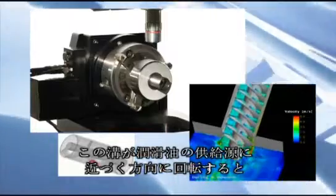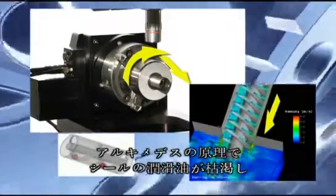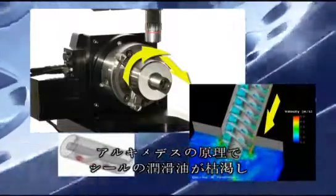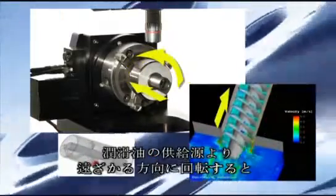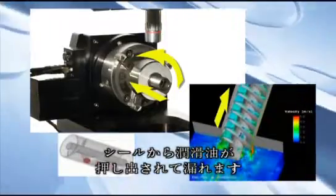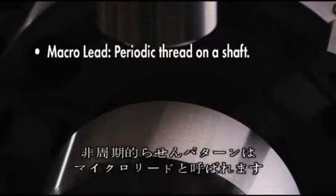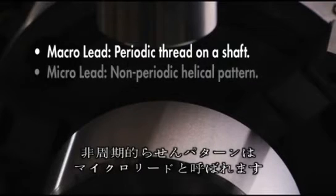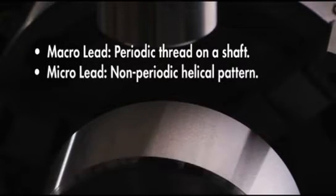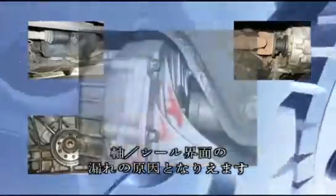Following Archimedes' principle, the presence of a positive thread moves lubricant in the direction of the source, causing the seal to dry out, while a negative lead pulls lubricant away from the seal, causing the seal to leak. Periodic thread on the shaft is called macrolead, while a non-periodic helical pattern is denoted as microlead. Macro and microlead both contribute to the overall leakage profile of a shaft seal interface.